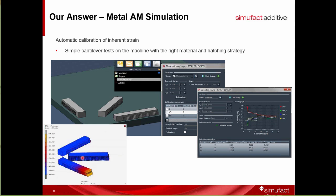So what we want to do is work with you to calibrate your machine and calibrate our software. You manufacture two or three of these little cantilever specimens using your hardware, with the power you're going to set the machine at, your speed, and the hatch pattern you're going to use.